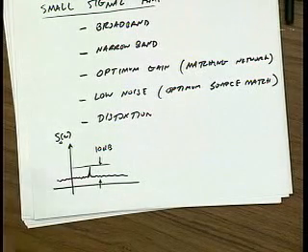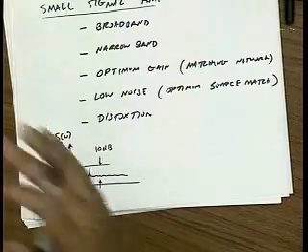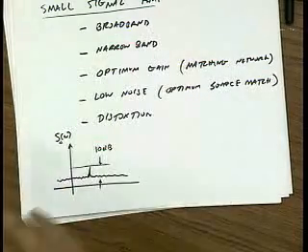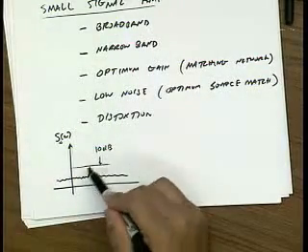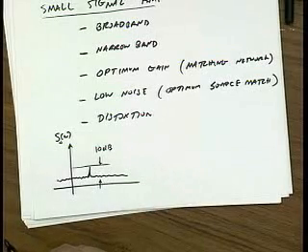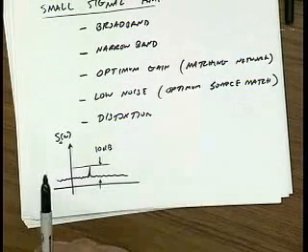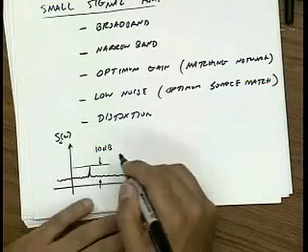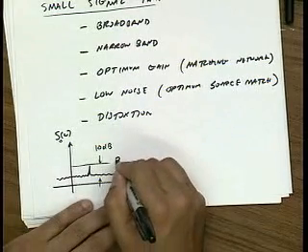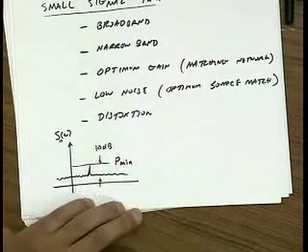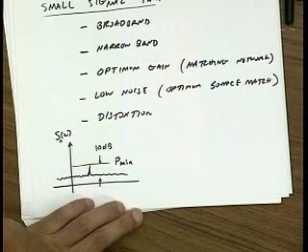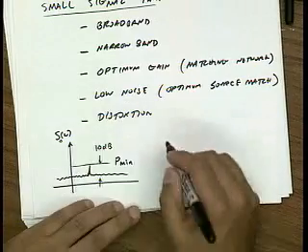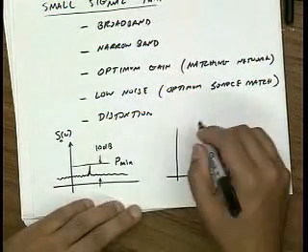Let's say that I know that I need a factor of 10 more signal power than noise power in order to figure out the information in this signal in the presence of noise. That's a system spec that you'll be given. So this pretty much tells me Pmin, the minimum signal that I can put into this amplifier and still get useful information out, right? On the other hand, if I now put in a really large signal,